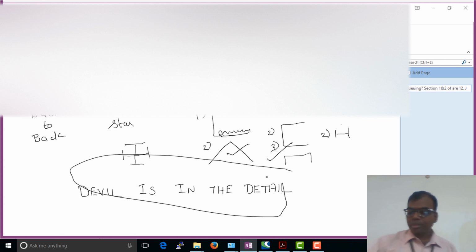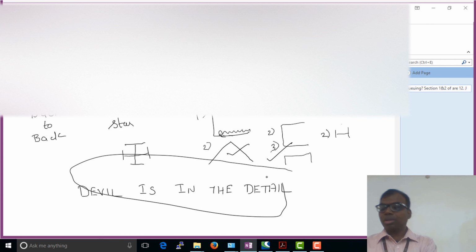Now again, of course, there are three other types of corrosion: stress corrosion, fretting corrosion, bacterial corrosion, and also hydrogen embrittlement. You can just know all of these for your personal information. But most of these you don't come across so frequently. These are things which you can avoid by how you do your design.